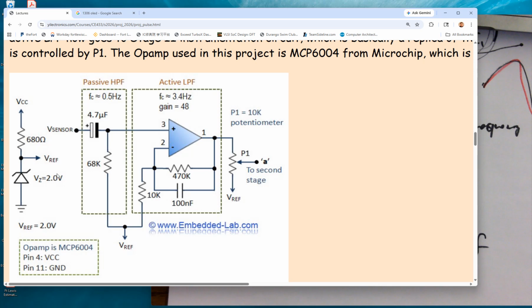But that's not even the most important part. The thing is, our ADC, even though our FPGAs are taking up to 3.3 volts as digital logic, the ADC is only taking up to 1 volt. That's a practical problem, right? How do we figure that out? It's given. The ADC is a 0 to 1 volt ADC for the input dynamic range. Anything higher than 1 volt will damage it. Divide it. Attenuate it. That's one of the ways to do it, right?